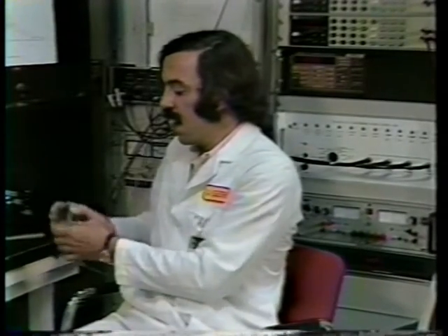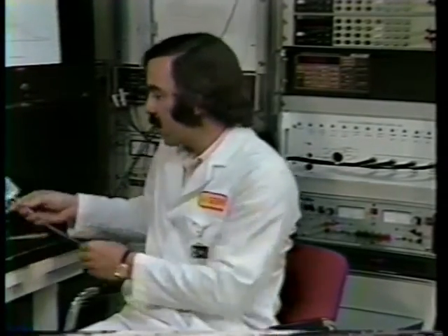Another important energy converter is the solar cell, which converts light into electricity. They're useful but expensive and inefficient, something which Keith Emery is trying to resolve. The first thing that I do to measure the efficiency of a solar cell is to set the intensity of my light source to be 100 milliwatts per centimeter squared. I need to use a reference cell which has been calibrated outdoors with respect to the standard solar spectrum. So I put the reference cell in, adjust the intensity of the solar simulator to be 100 milliwatts per centimeter squared, and then place the cell that I am going to test inside of our test station.